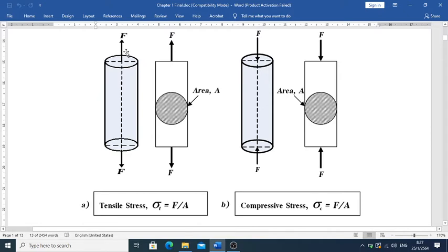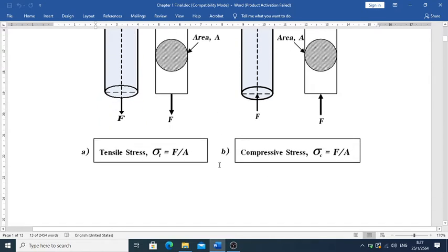What you see up there, the tensile, is positive. The figure on the left is positive. Inside is the cross-section area, with small forces distributed all over the given section. On the right-hand side, we have a compressive stress, a compression force compressing all the way, distributed over the given section. You may denote sigma t as tensile and sigma c as compressive, respectively.